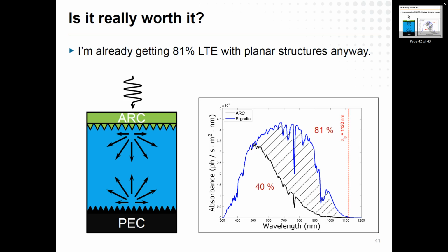that have to be weighed for. So this idea of, yes, in principle I might get absolutely like 98% light trapping, but now the cost has gone way up, and all it gave me was an extra 20% boost in my efficiency. What if, instead of being 1 micron, I just made it 2 microns? Then that might push this from 80 to like 85 or 90 or something, for all you know. So there are simple solutions to get what you want, and then there are big, horrible, complicated ways to go about it.